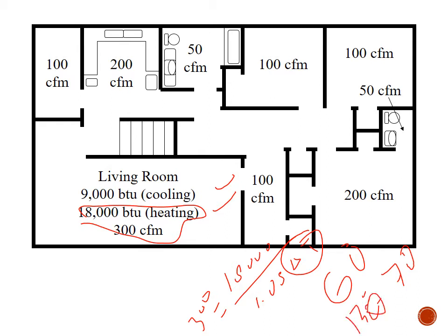That's very hot. My delta T here became 60 degrees based on this calculation, which is a pretty high temperature. But again, this is how it's done. So what you will do in your project is plug in your BTUs, plug in your desired delta T, and plug in your heat capacity for air, and you will get your CFM here. Okay.